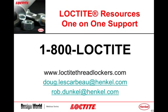Okay. What type of thread locker would you recommend for a high temperature application? We have two different products. It's probably best to consult our catalogs for it. Most of our products, the older generations, were good to about 300 Fahrenheit. The upgraded ones we've brought out are good to 360 F.